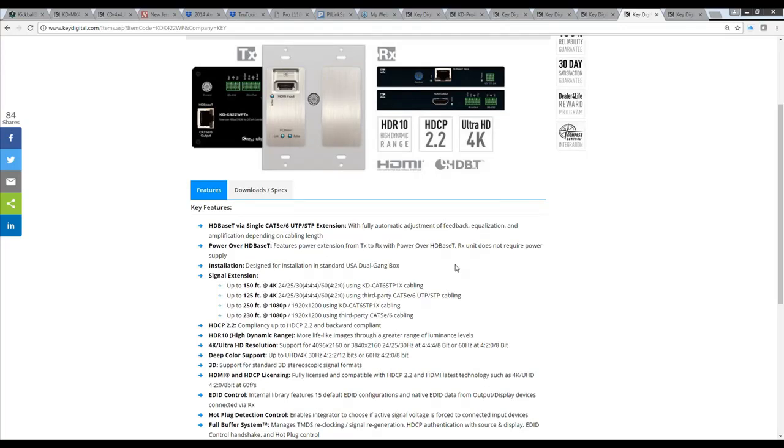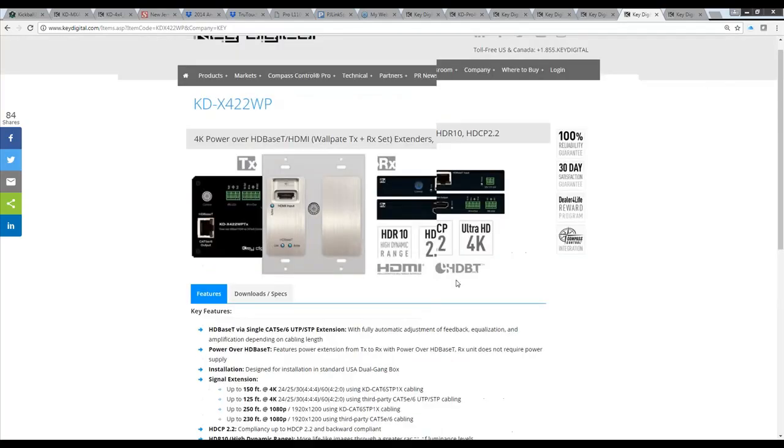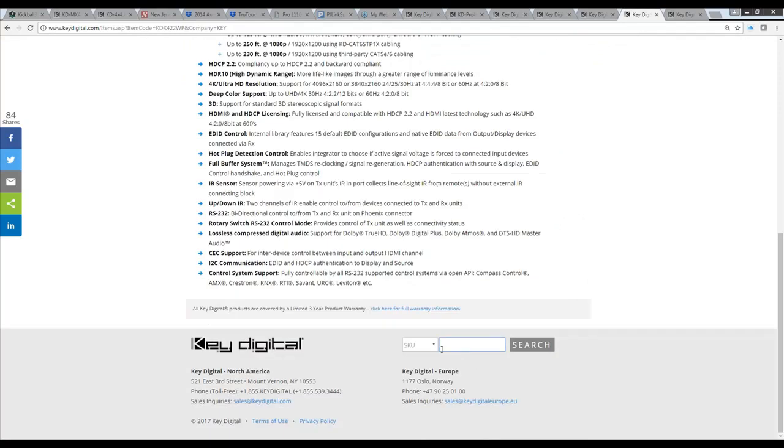The reason I say that is because shielding just helps to prevent interference from coming into the cable. And interference in the digital world, you may not notice it until it's so bad that it causes the signal to drop. If you're running near an elevator and they call the elevator and then all of a sudden you have no picture on your screen. You've heard of that before, and it's hard because there's nothing you can do, because electrical interference is so severe that it's totally corrupting the signal. The signal's not coming through anymore. So using shielded twisted pair cable will help you avoid or prevent that.